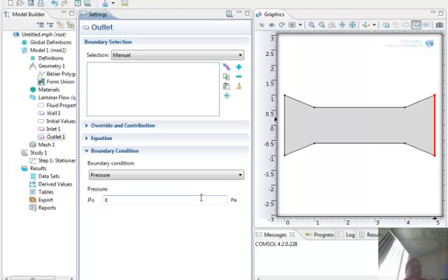Okay, so it is coming out. And remember, in incompressible flow, what did we learn? The absolute pressure magnitude does not matter because it's all the gradient of pressure that appears in the equation. So if you fix the pressure as 0 and you calculate the pressure here to be 2, that pressure gradient is 2 pascals per meter. So it's relative. You can fix the pressure at the exit at an arbitrary value.